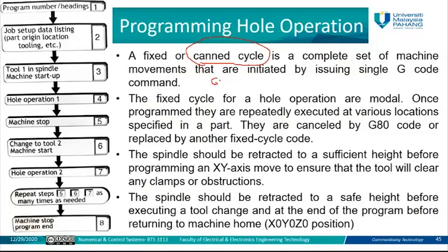Sometimes the spindle goes to the workpiece from the wrong coordinates, or the space between the workpiece and the spindle is not enough, or after creating the holes there is no clearance for the material inside the holes. All this will affect the quality of the produced holes on the workpiece.